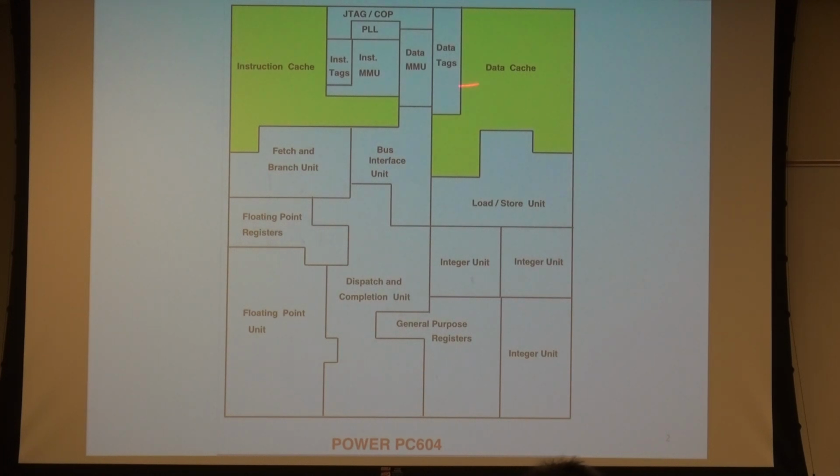We will later on throw in some memories using some generators for instruction cache and data cache. There won't be any phase lock loop because your chip is small, so it doesn't require synchronization of clock at different places.